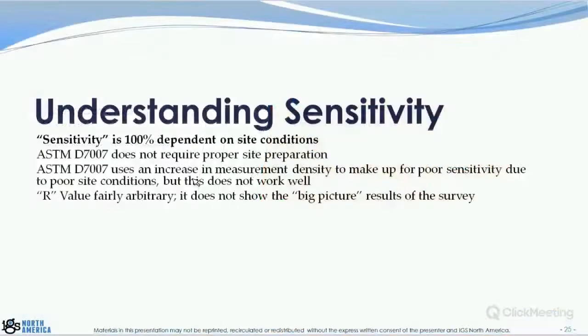So transitioning from data analysis to what makes a survey sensitive. I'll tell you right now that sensitivity is 100% dependent on site conditions. The ASTM D7007 doesn't require proper site preparation. It details what should be done, and I'm quoting from the ASTM, "if practical." So if practical, you isolate the cover materials from the subgrade. If practical, you need to add the adequate moisture.